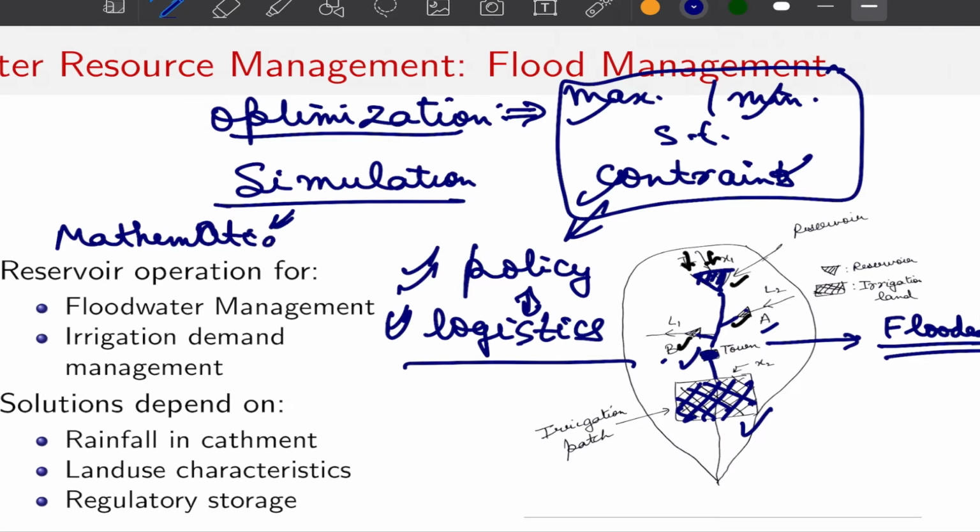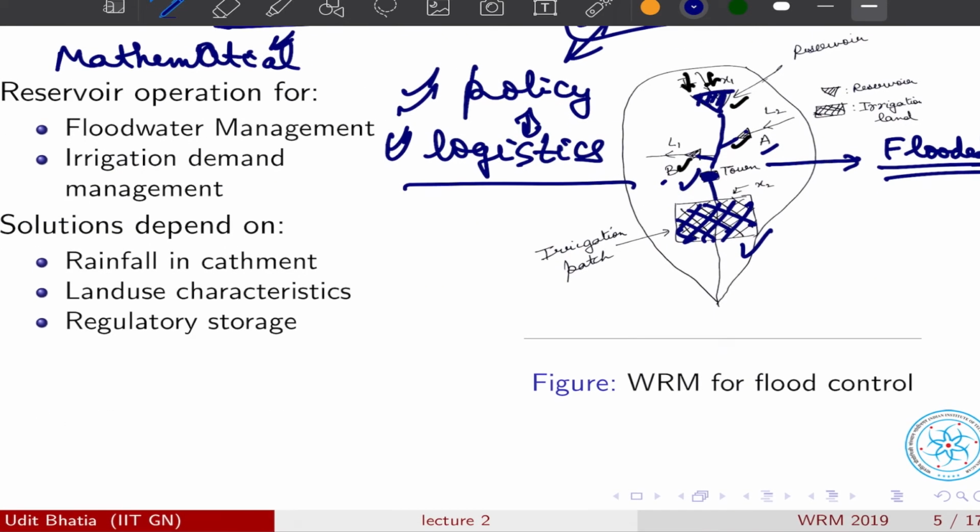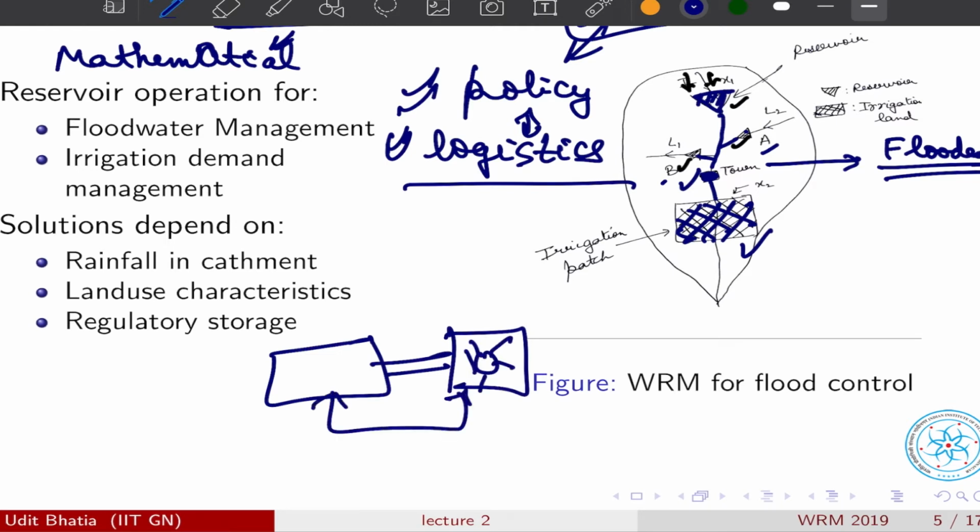So we want to understand, without building a dam, how much of the area would benefit from it, or how much hydropower electricity we could generate. So what we will do is set up a simulation model without worrying about an objective function. We will try to set up a hydrological model, for example. From the hydrological model, we will try to set up a model for the turbine, and we know what kind of energy transformations are happening, from potential energy to kinetic energy to electrical energy finally.